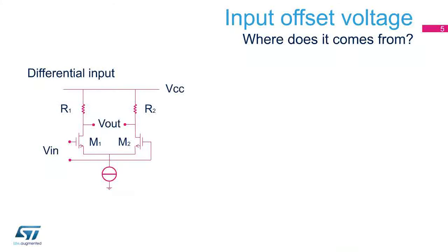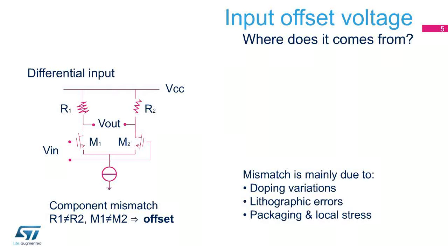The cause of the input offset voltage is well known. It is due to the inherent mismatch of the input transistors and components during fabrication of the silicon die, and the stress placed on the die during the packaging process, a minor contribution. These effects collectively produce a mismatch of the bias of the input circuit, resulting in a differential voltage at the input terminals of the op-amp.